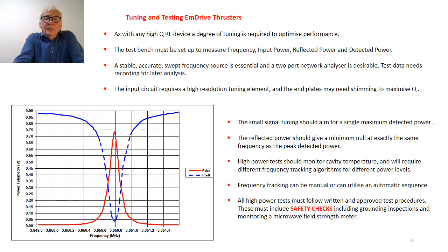And what we did was to develop frequency tracking algorithms to enable us to carry out this frequency tracking, which initially was done manually. But clearly for flight equipment, you need to utilize automatic frequency tracking using a closed loop control system.